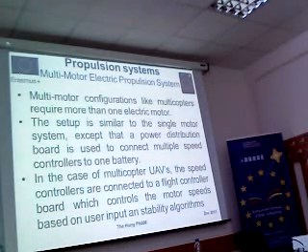And in the case of multicopter UAVs, the speed controllers are connected to a flight controller which controls the motor speed based on user input and a stability algorithm. The stability algorithm is the kind of controller I have shown you yesterday and this morning in the video.